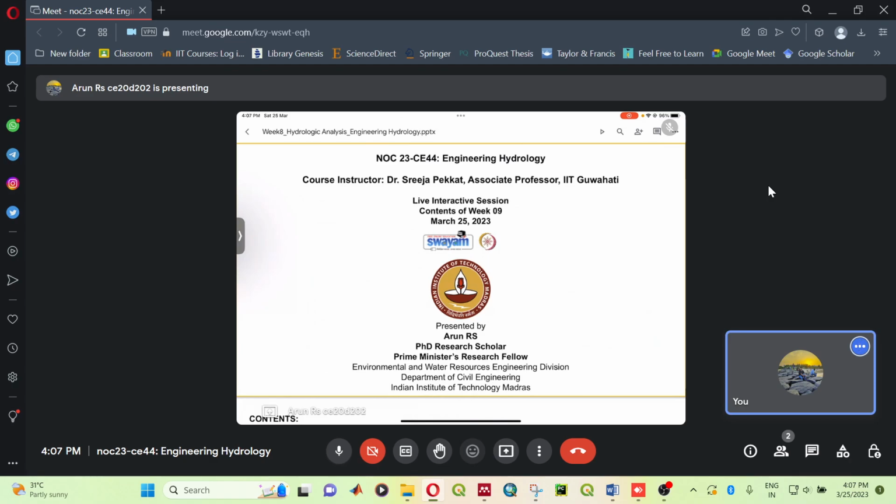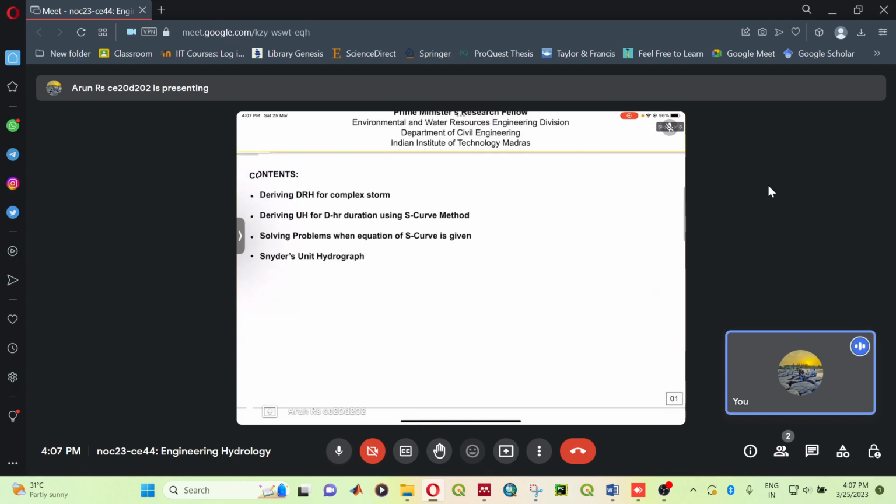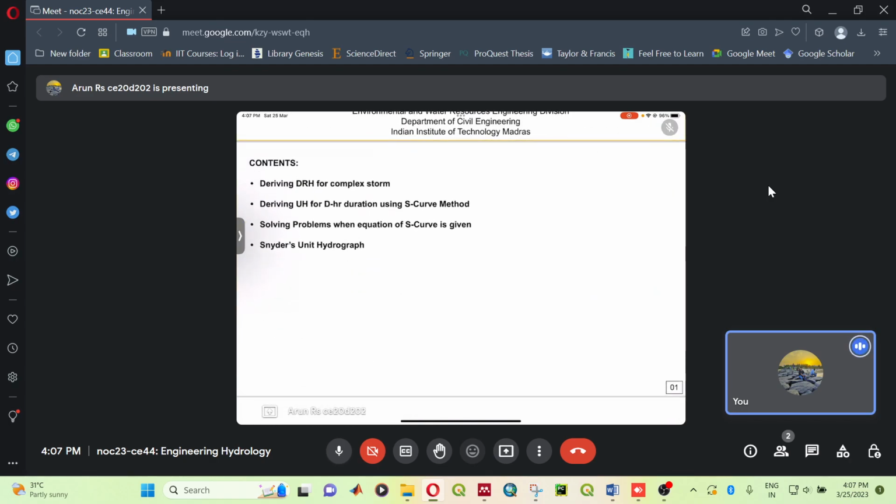So we'll be seeing the contents of week 9 in this live session, which is the topic related to the hydrologic analysis. And in this week we'll be seeing how to derive the direct runoff hydrograph for a complex storm. So you'll be given unit hydrograph coordinates and we'll be given some rainfall values which occur consecutively in each hour. And for this kind of storm event, we need to derive the direct runoff hydrograph.